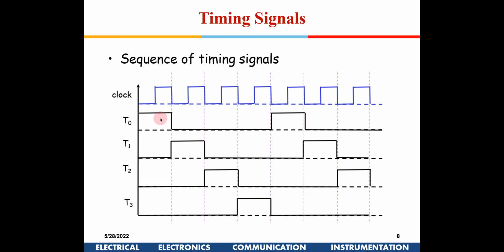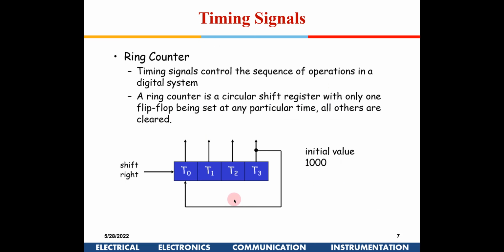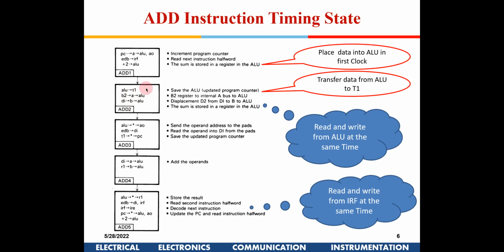So for the same clock, I have now generated 4 out-of-phase signals. They are all 90 degrees out of phase, you could call it. They are T0, T1, T2 and T3. These are known as multi-phase signals. These kinds of signals will enable us to use the same clock frequency but do multiple actions. How that is done, we will see.